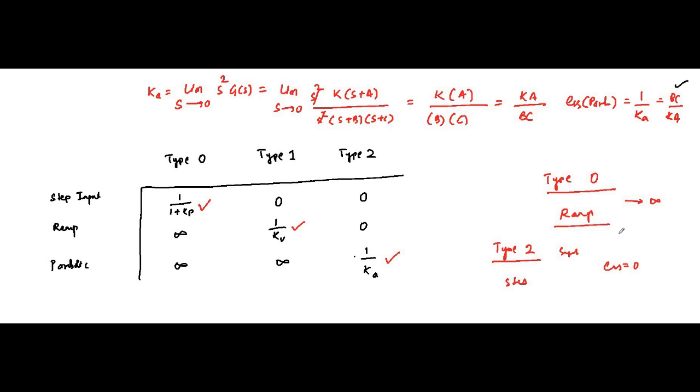But in case of subjective type questions where you have to do the step-by-step process, you should not use this approach. There you go by the previous methods, the way I have done the previous questions. You have to first write the open loop transfer function, then calculate the error coefficients, whether position, velocity or acceleration, and then get the result.